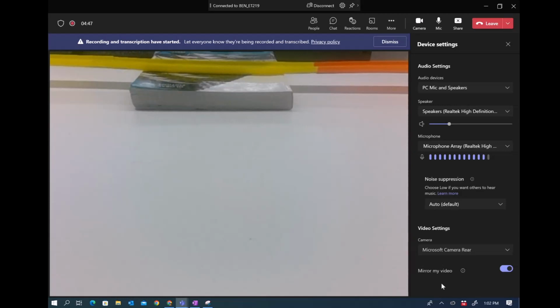This beam that we have has a pin support and a roller support, so three unknown reaction forces and 3 equilibrium equations, and this is doable: finding the reaction forces, finding the deflections, drawing the shear force diagram and the bending moment diagram. Now from this week, we have added extra complexity.